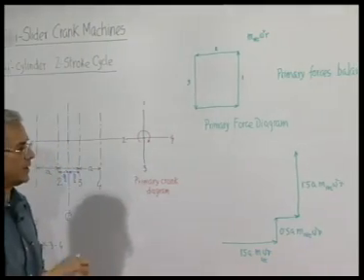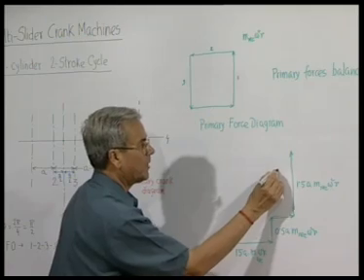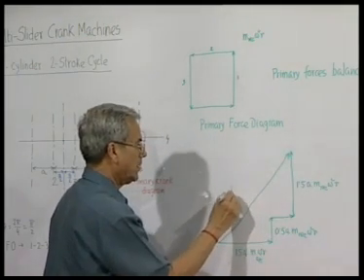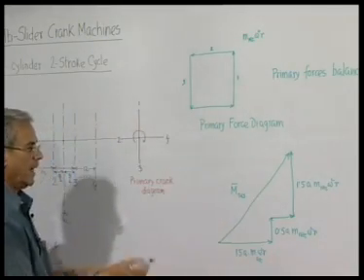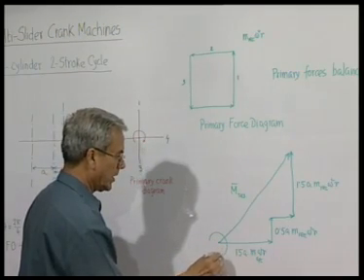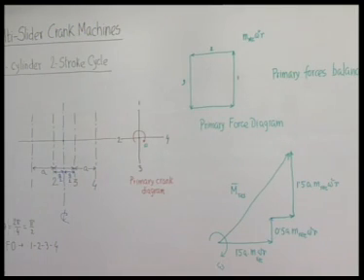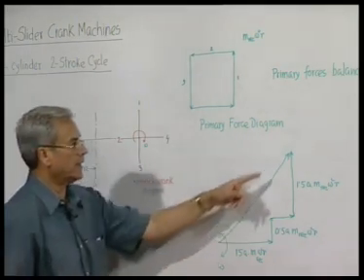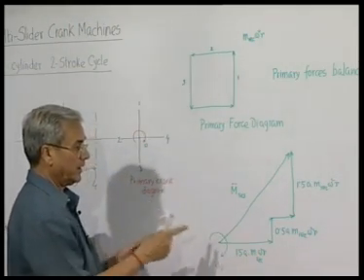So, the resultant moment, you can see it does not form a closed polygon. So, this is the unbalanced moment, that is a vector quantity, and the whole diagram is rotating. Of course, you have to see that this whole thing is rotating with the same speed omega as the crank. Just like a rigid body attached to the crank itself, the whole thing rotates, and the resultant being this at certain angles. But remember, the actual moment is not this one.